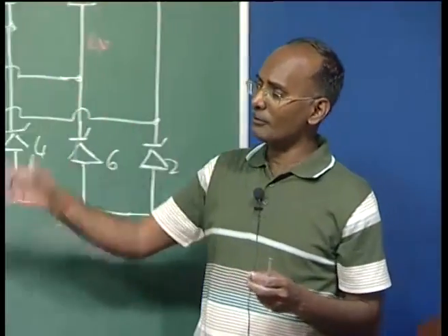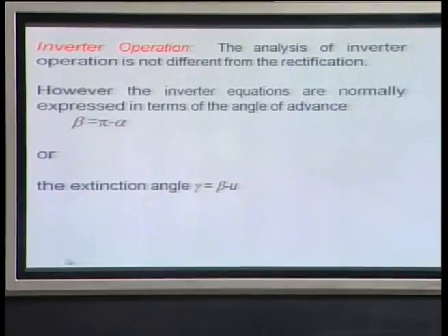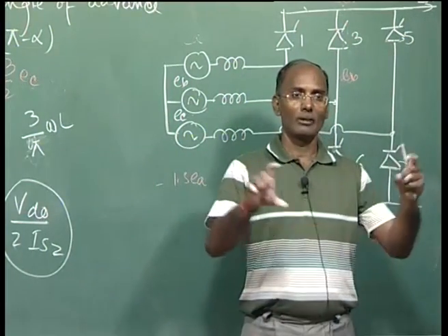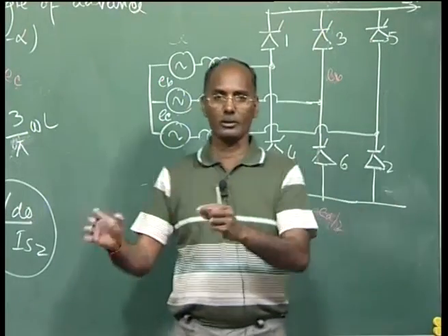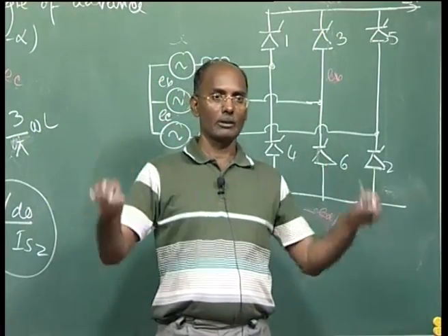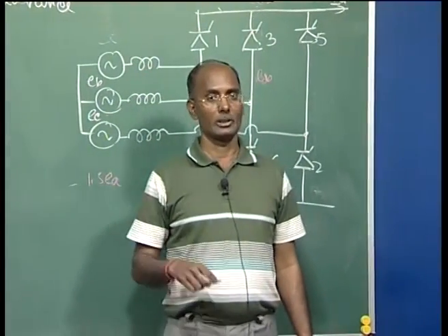We'll see in the next lecture how this inverter operation and the voltage of the valve will work, and then we'll again model the equivalent circuit of this inverter operation. Then we'll connect by the DC line, and see the whole rectifier and inverter represented by an equivalent electrical circuit, and that will be used for control algorithm design.